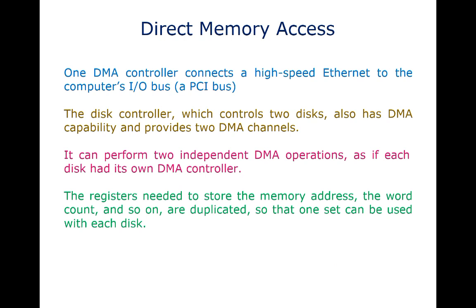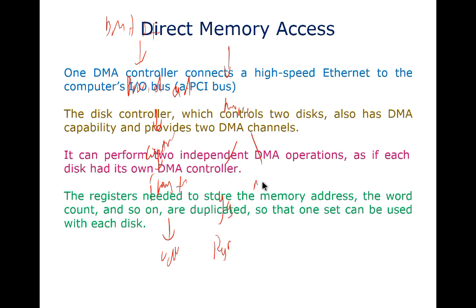So the DMA transfer operation performs this as a flow: first the DMA starts, so direct memory access starts, then it provides the address, then control signal generation, then transferring of the word, then updating the address. After that, if more data is available, it will repeat that process. If not, it will give a signal as completed.